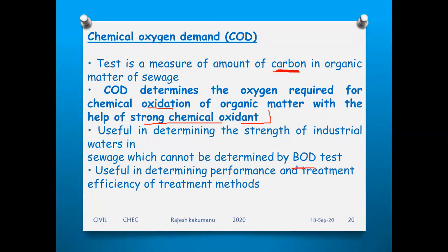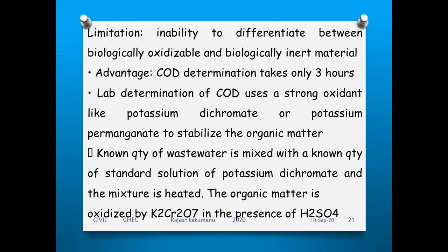So in some cases of the BOD test, there is no possibility of calculating the oxygen content. But in this COD analysis, it is useful for determining the strength of industrial wastewater in the sewage. Next point, useful in determining performance and treatment efficiency of treatment methods. The COD analysis is useful in determining the performance and treatment efficiency of the treatment of the water. Next, what are the limitations of COD?